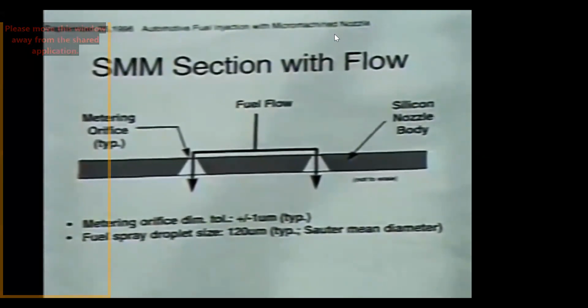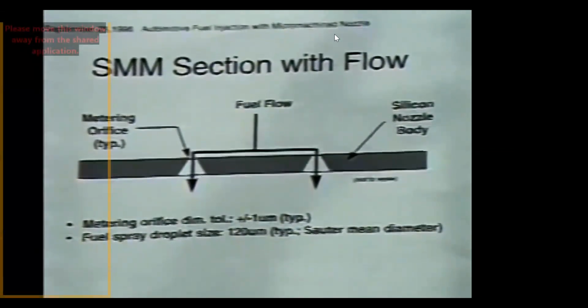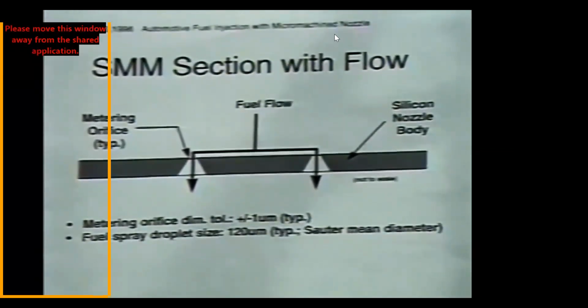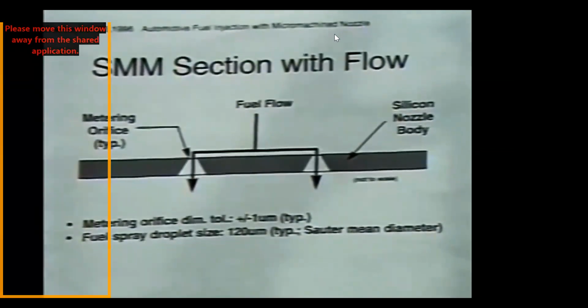The third thing, which is not shown here, is deposit resistance. The intake environment of the engine is a hostile environment, and basically you need something that resists the amount of foreign material that attaches itself to the injector. This prevents the clogging of an injector and the reduction in flow.